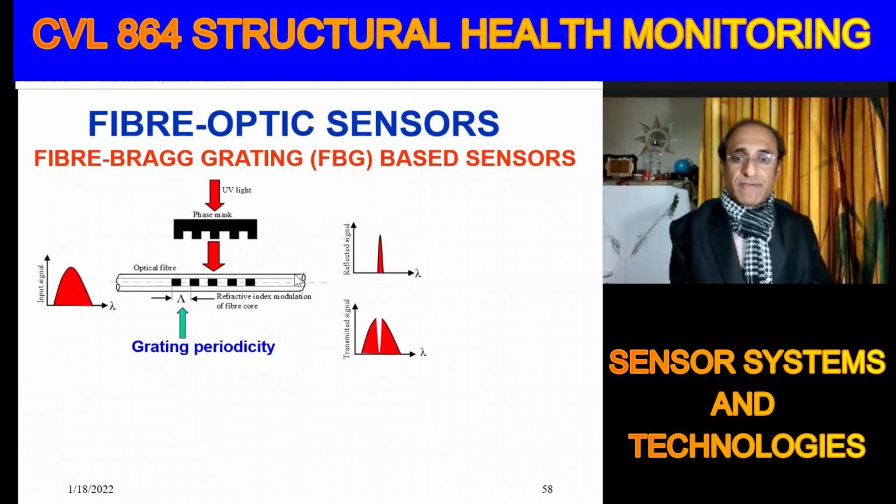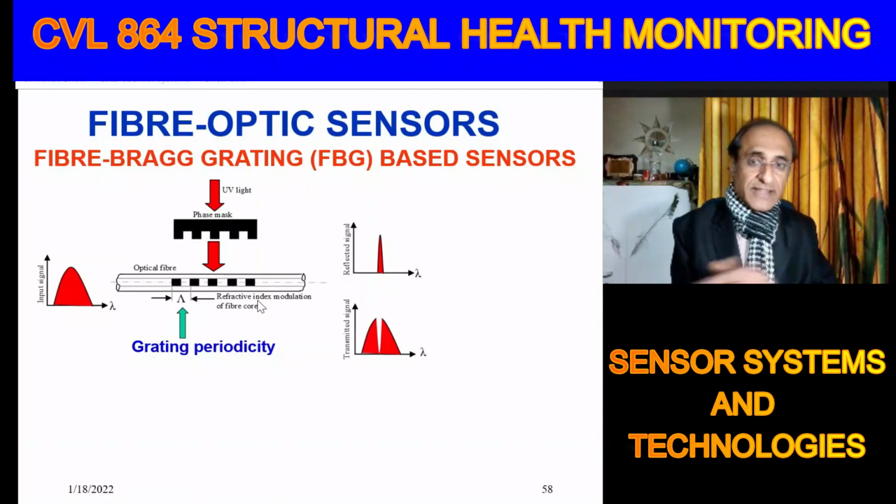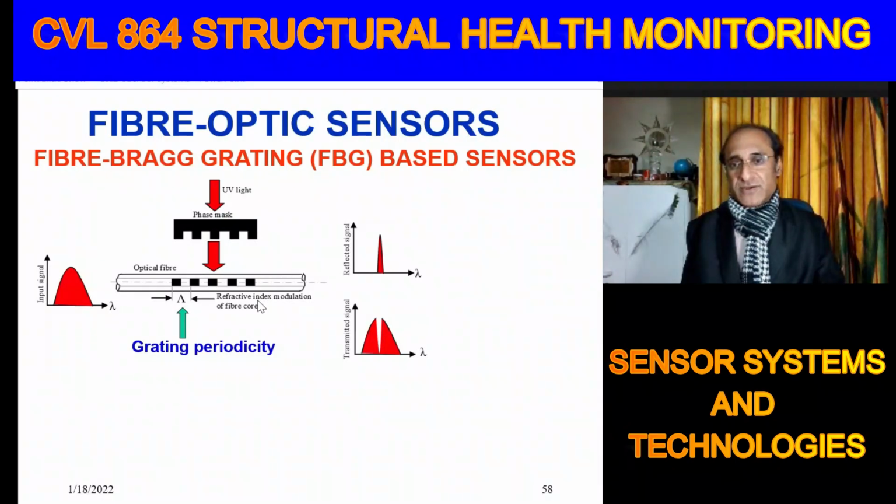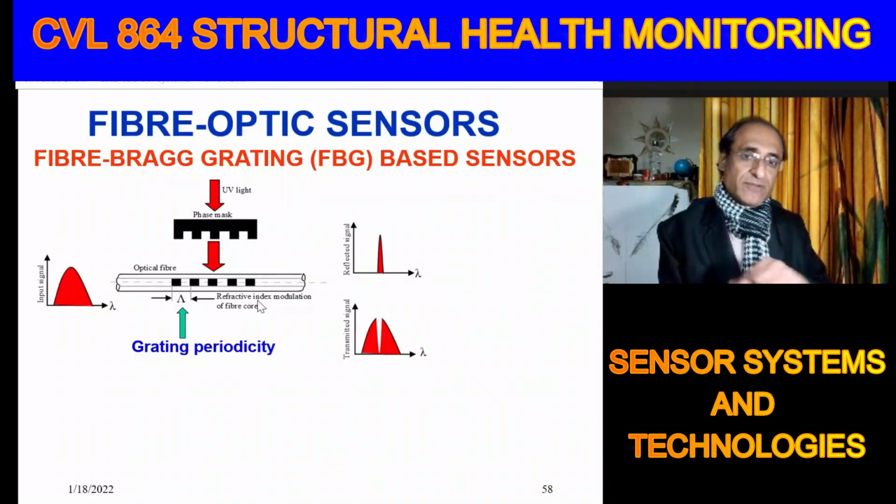And this Bragg wavelength is very much dependent on the periodicity of these gratings, because we have created these gratings and filters, and we can choose the linear distance between them, and by this we can tailor-make our fiber such that it reflects a particular wavelength.